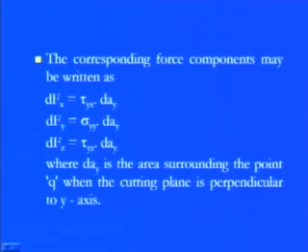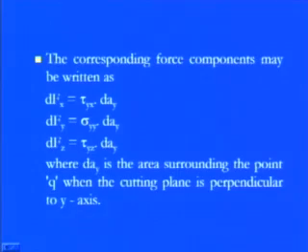So obviously now the parallel stress components are there, which means there are no perpendicular ones. Now you see the shear stresses are always dominating in this kind of situation. So dFx is nothing but equal to tau yx times dAy. Similarly, if we go to dFy, you see, this is my y domain and it is just perpendicular to the y plane.